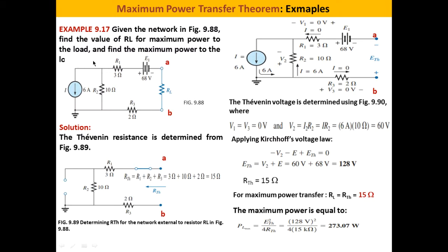So you can see here we have applied the Thevenin theorem to simplify the circuit, to determine R Thevenin and V Thevenin, and also to calculate the maximum power that can be transferred to the load, and the load we have to set to get this maximum power transfer. So we have done analysis plus design. We have selected the load in order to get the maximum power transfer. You can see how these theorems help us to analyze the circuit in an easy way.